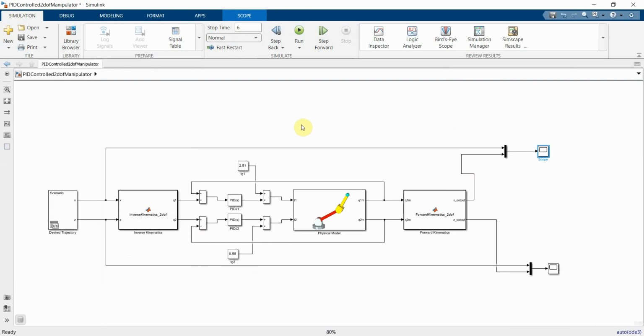Another approach which is recommended is to create an optimization algorithm and a cost function to calculate the difference between the measured joint angle and the desired joint angle, and minimize the difference by changing the parameters that are defined in the controller. So in order to do so, we have to have a script performing this calculation for us.